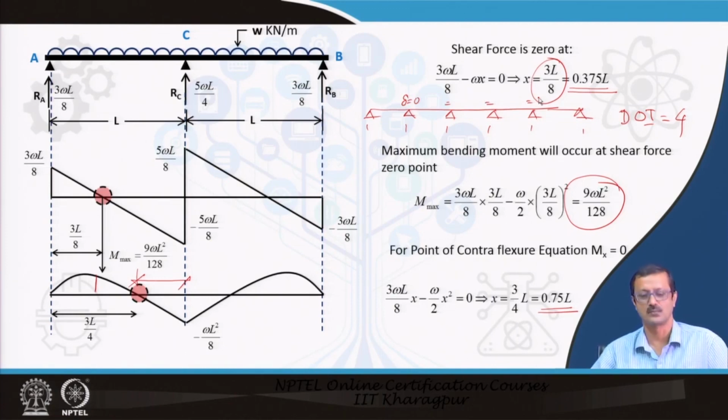You know, in large buildings you may have 12 spans, 15 spans, sometimes 20. In hostels, there are series of rooms. In hotels, series of rooms. It may be 20 such bays, 20 spans of continuous beams. The 20 spans of continuous beam will have 18 unknowns. DOI is 18. There are 18 equations that can be formed, but how to solve 18 equations manually?